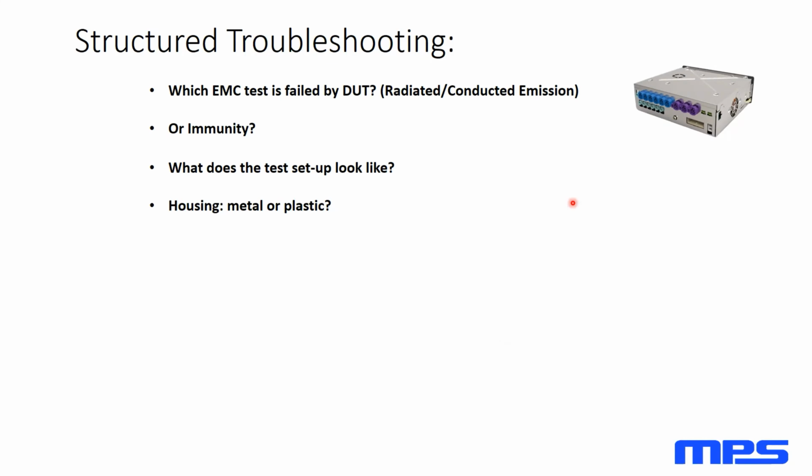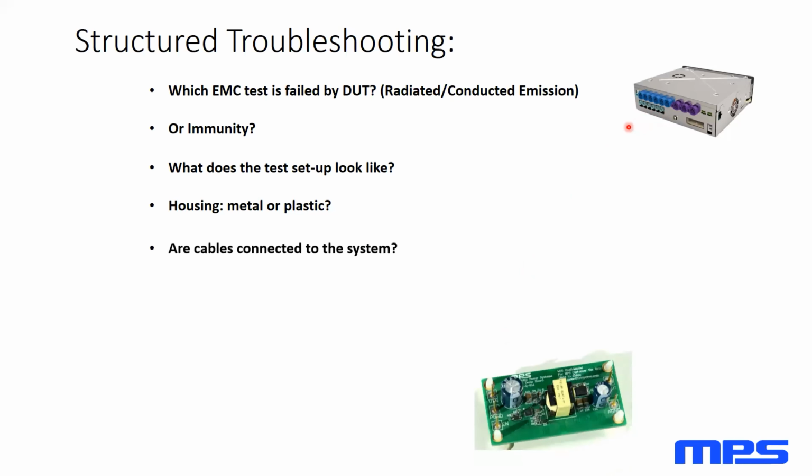This picture we have in the upper right, it's kind of tough to see, but there's openings around these connectors here. And depending on what is going on the other side of that, this can become a slot antenna and cause problems for us. So this is not necessarily a good shield being inside a metal enclosure. So we need to think about what's going on behind that portion of it, or even in other areas of the circuit.